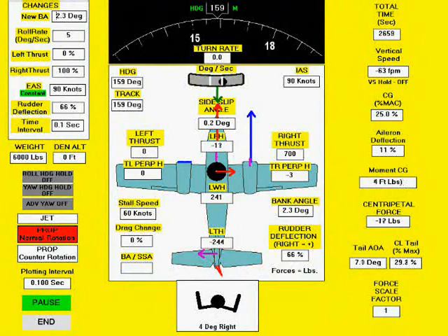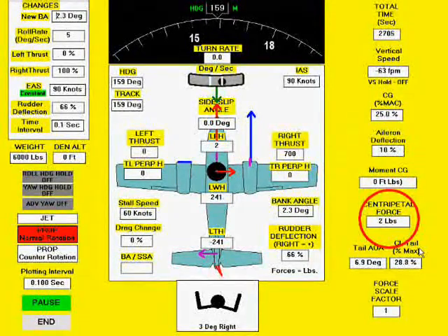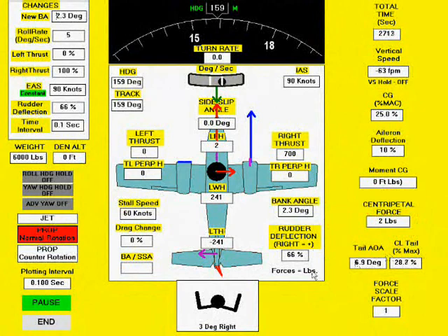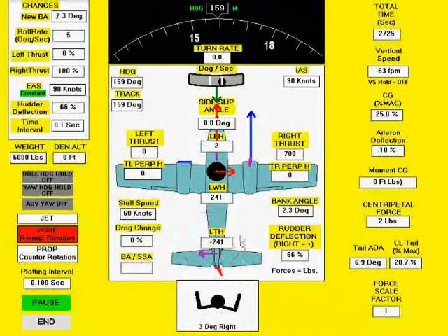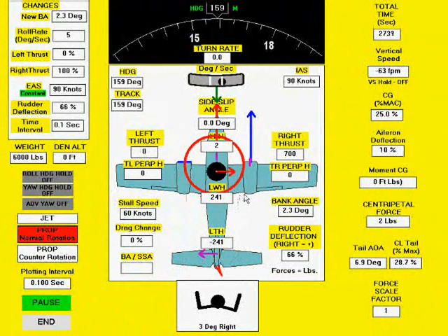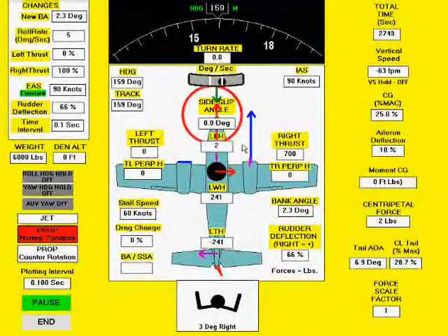Horizontal wing lift now cancels the vertical tail lift. With slightly more than 2-degree bank angle toward the operating engine, we are able to maintain a 0 sideslip angle. Note the right ball deflection. This is to be expected since when no turn is occurring, the ball sits in the lowest point in the raceway. This 2-degree bank angle is typical for light twin-engine airplanes.